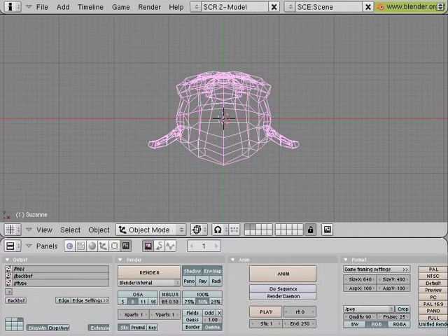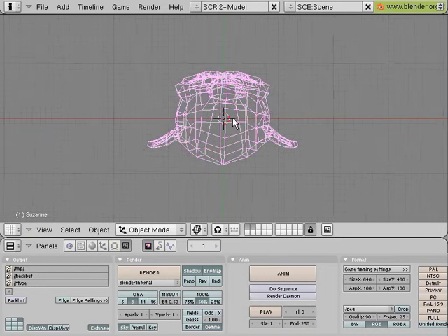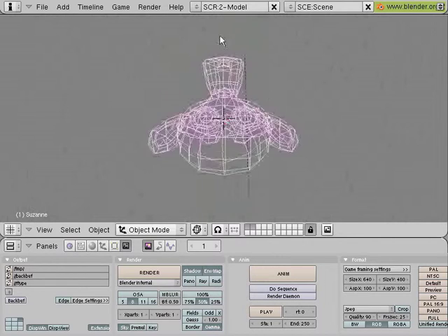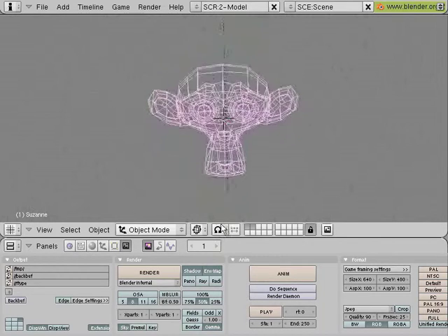Alright, so aside from those, you can also rotate, zoom, and translate the view any way you like. So let's start by doing that. Click and drag with the middle mouse button on the viewport area. Okay, remember that middle mouse button. Remember how I talked about how the interface uses the middle mouse button a lot? Well, this is when you start to realize this. Okay, so hold down the middle mouse button, and let's say we start at the center, then click and drag, and you can see that it rotates the view from the center.